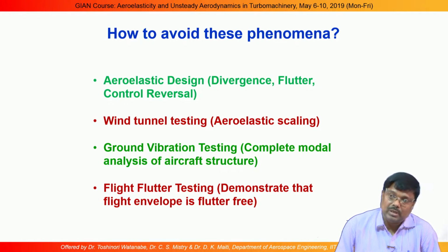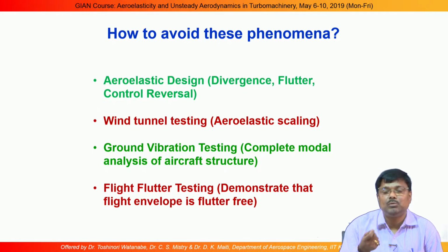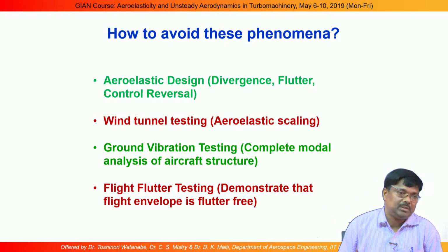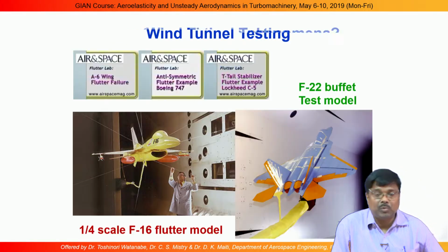Then once the aircraft is ready, we need to do the ground vibration test, then the flight flutter test. That is when the aircraft is cleared for flight. There you have to demonstrate the damping: the pilot will give a certain pulse and the responses are measured, and then the ground engineer will do the calculation to confirm that the damping for each of the different modes is above 3%. So it can proceed to the next test points.